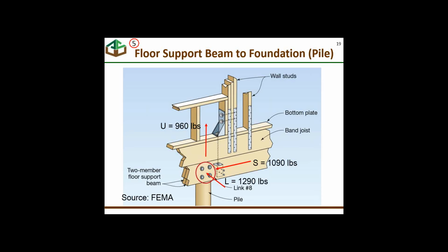I want to go back to one point made last week to just clarify something. So you see the connector that is right here, this hold-down connector that's at the edge, in this particular case, of a window. This hold-down connector was illustrating a hold-down required in this segmented shear wall. And I mentioned last week that these connectors are used and need to resist both tension and compression.